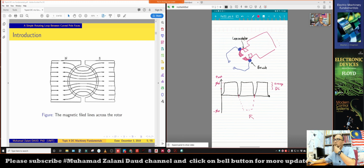As you can see, this is the design of the commutator for a single loop. This commutator has a brush attached, which is in contact with it. When this wire loop turns, at some instant, when this segment reaches 180 degrees, for example, it will change polarity.